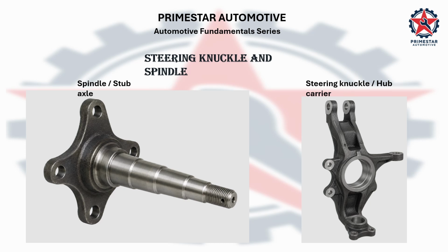Driven hub knuckles are also used on some front-wheel drive and all-wheel drive and many independent front four-wheel drive vehicles. It has a large center opening and the CV shaft, or constant velocity drive shaft, passes through the wheel bearing and spline hub.